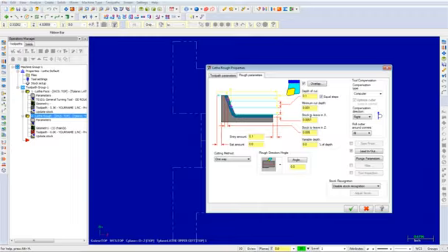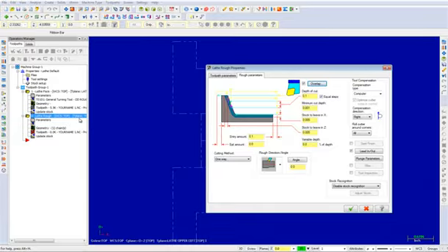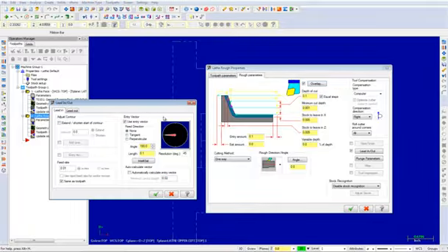Now select the overlap button and input an amount of 0.05. Select the OK button to exit the Rough Overlap Parameters dialog box. From here, select the Lead In Lead Out button and choose the Lead Out tab to extend the end of the contour as shown. Change the value to 0.125. Once completed, select the OK button to exit the Lead In Lead Out parameters.